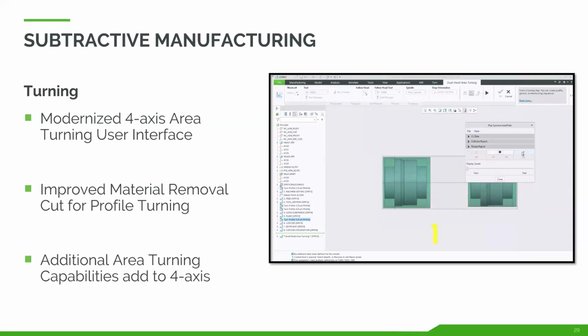There's a series of turning capabilities that we had introduced for 2-axis back in Creo 10. Well, we've now added them in Creo 11 to the 4-axis. We can now specify something like cutter compensation per slice, the better control over the clearance distance, better entry and exit controls for the toolpaths.